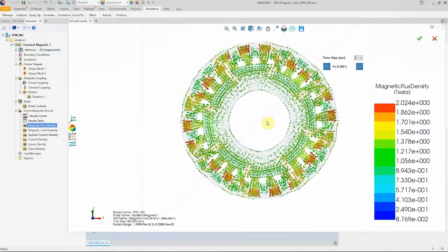can cause some problems in the high speed rotor, and the eddy current loss in the field modulators or even the magnets will make some problems in heating. Core loss will increase the temperature of the system, and we always have problems with the temperature. Demagnetization risk will be increased in higher temperatures. These are the limitations of the speed.